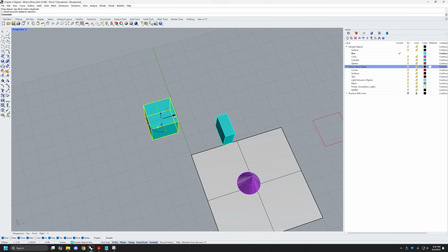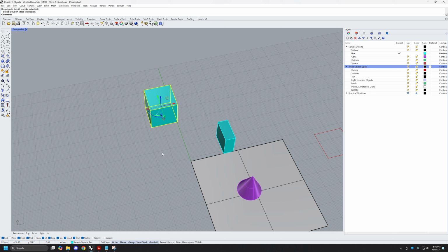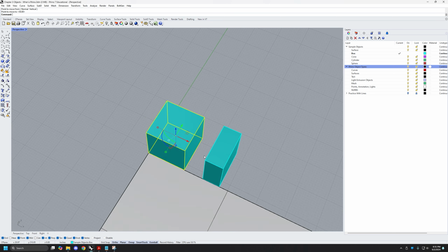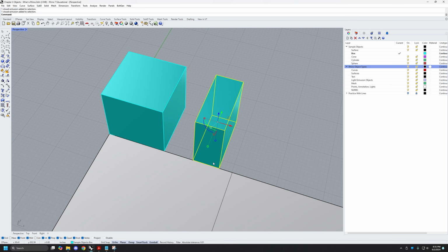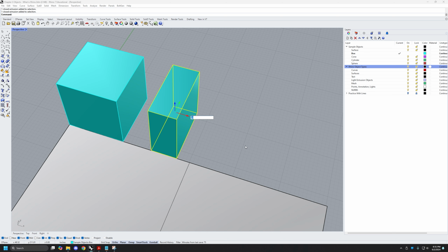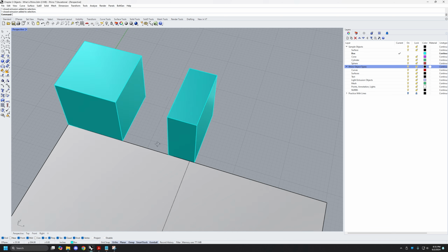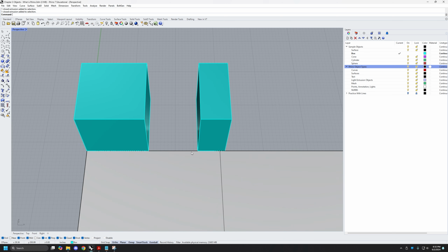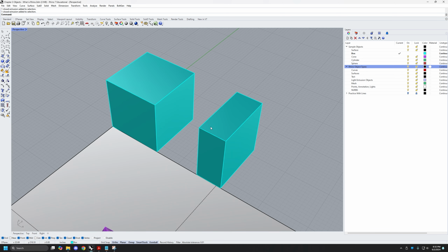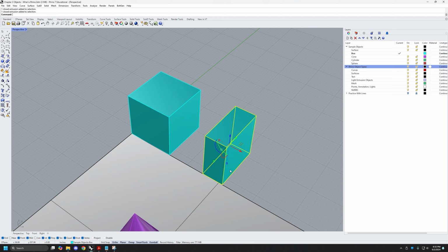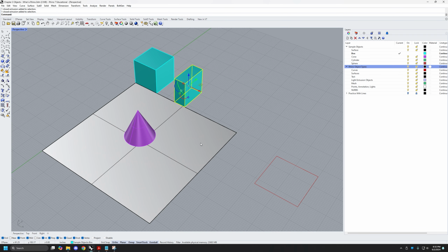And you can also be precise with the gumball. Once you have your object placed, like we did earlier, we know that this distance is the midpoint. So from there, you could say, okay, I want to go 5 more units, because then that'll give me a total of whatever my increment is. Once you have an established baseline, you can use the gumball relative to its current position. But moving things precisely with the move command is super helpful. And there are some different options for you.